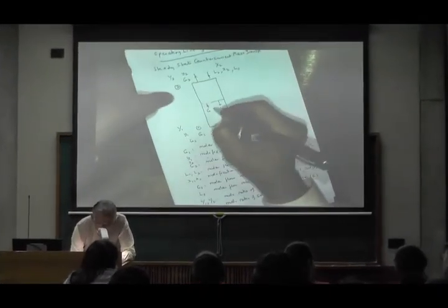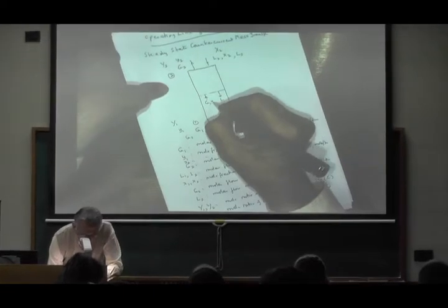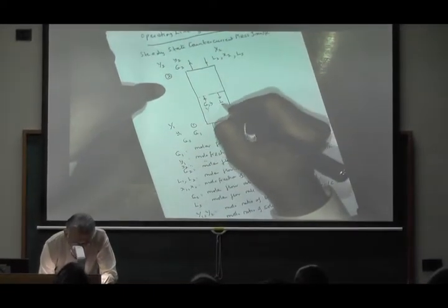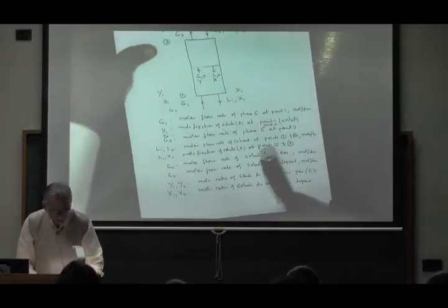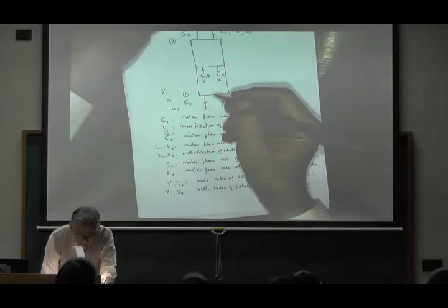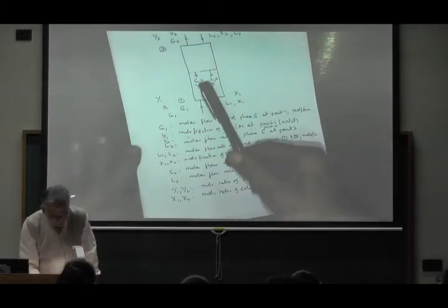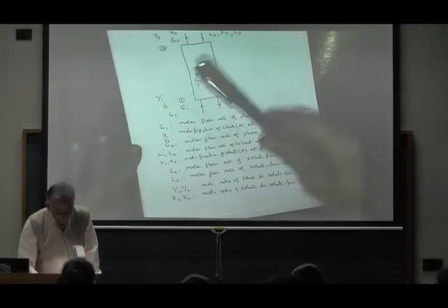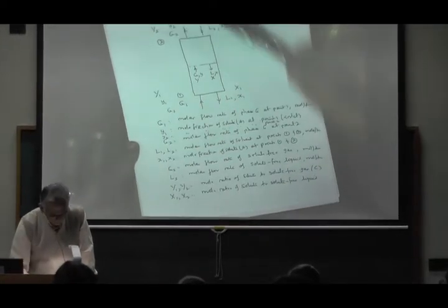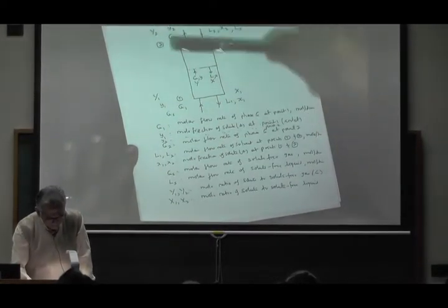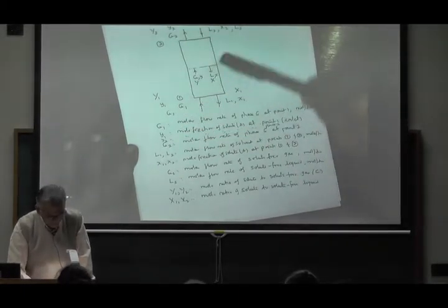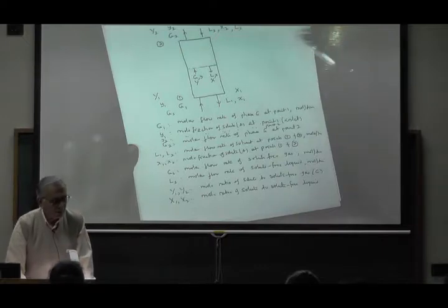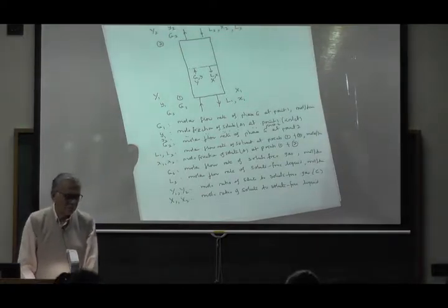Let's say here we have any small y, any capital Y, any small x, and any capital X. G, small y, and capital Y are changing along the length. Similarly, L, small x, and capital X are changing along the length. What is not changing? GS is not changing. LS is not changing. So if absorption is going on, how can we say that the solute-free gas is constant? Like it will change.